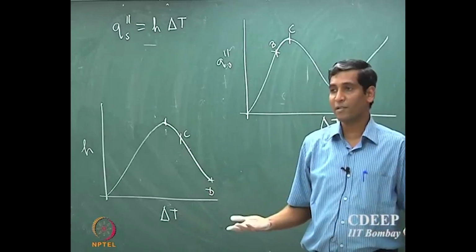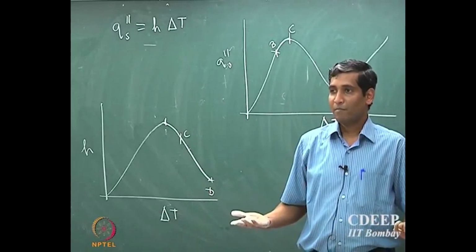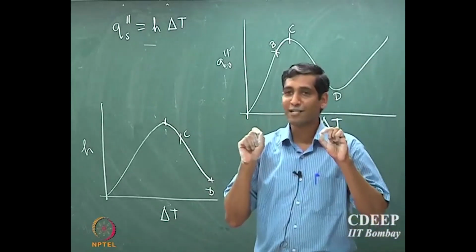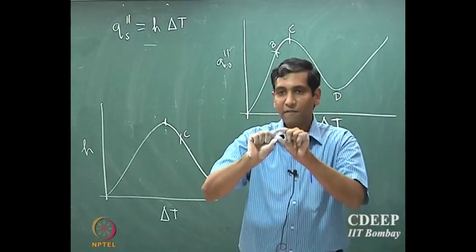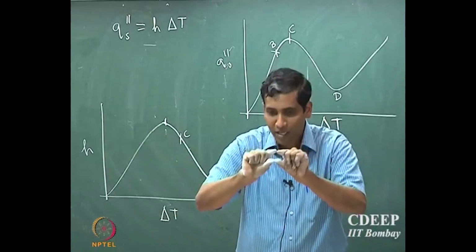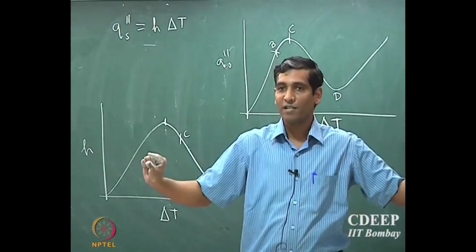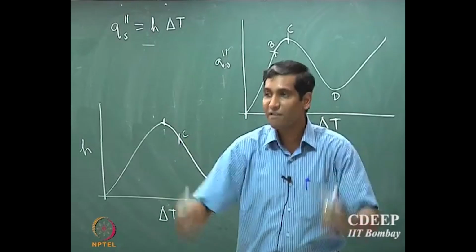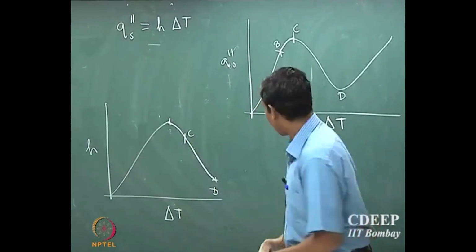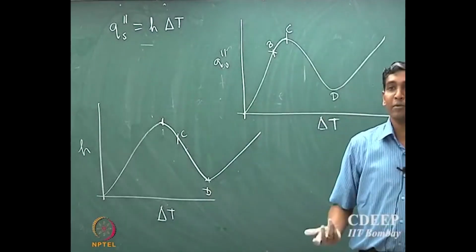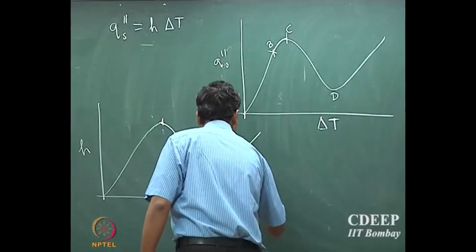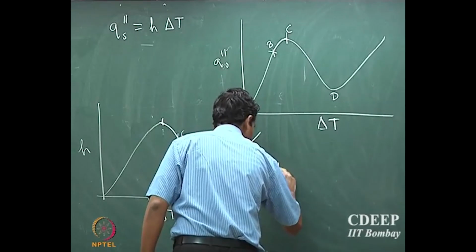After that it's a single phase system, because whatever fluid comes to the bottom is instantaneously converted to the vapor phase. So there will be a film of vapor which is always present on top of the bottom surface. Therefore it's now a single phase heat transport process, and the heat transport is simply going to increase as you increase the temperature difference. There are no multiple phases here.